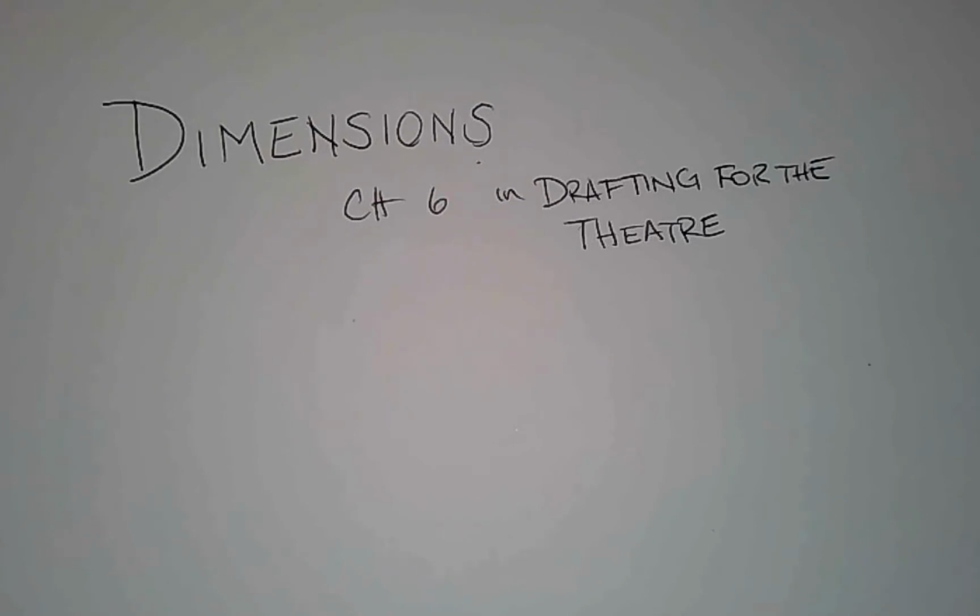Okay, so here we go into the land of dimensions. Dimensions are part of the notes, and the dimensions together are the annotation of the drawing that provides enough information for the shop to build it. So the rule of thumb there is, can the specifications provided be interpreted only in one way, and are they complete enough to build and finish the project without additional information?